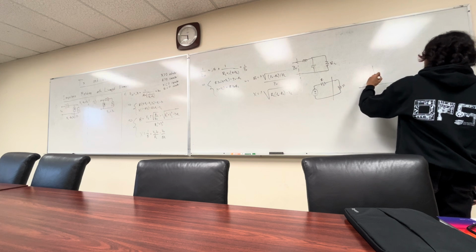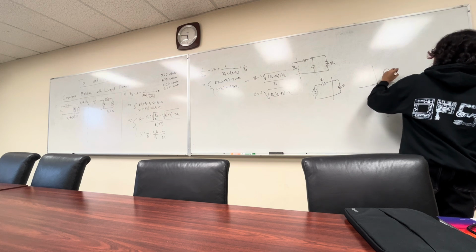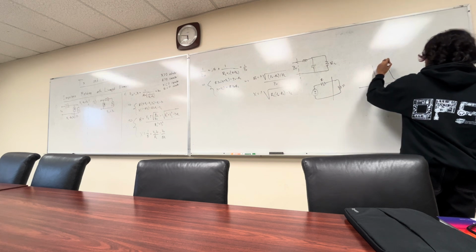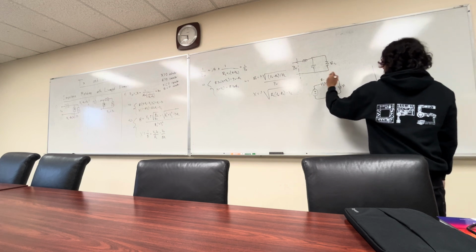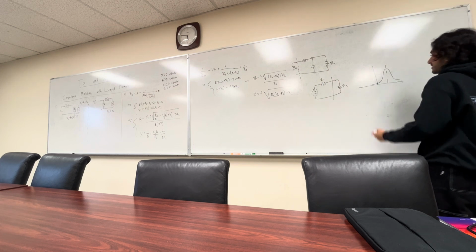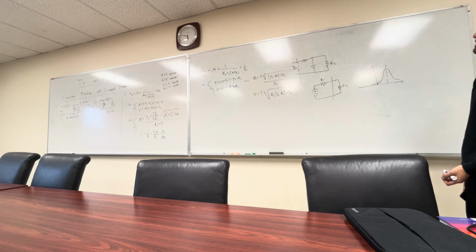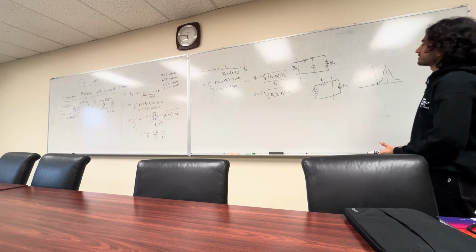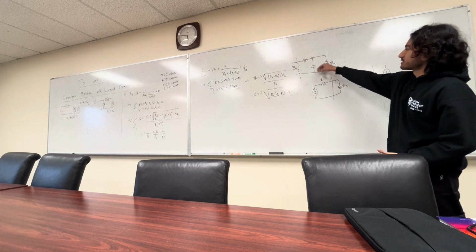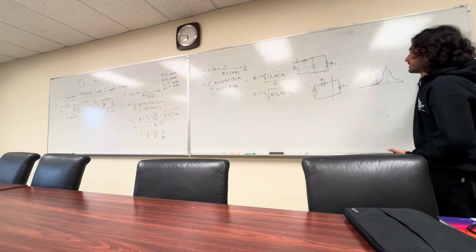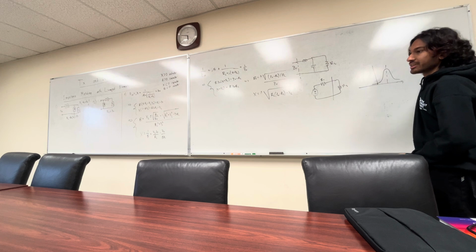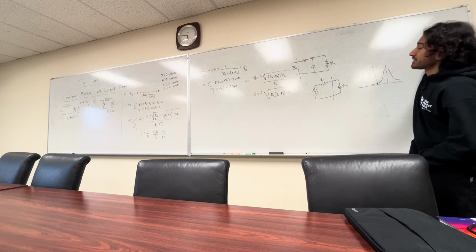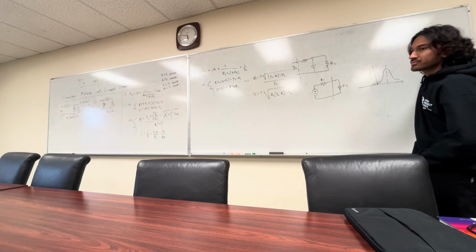If you look at the curve, you get something that looks like this. Maximum only here when R1 and R2 are equal, but if you stray away, power transfer goes down. So effectively, as you go away from this resonant frequency, the conjugate match is changing, and other signals get attenuated. That's kind of useful. So you have both the properties of a filter and a matching network.